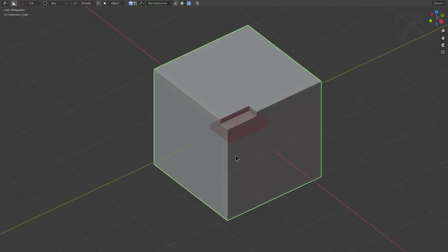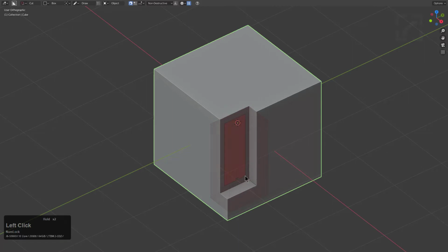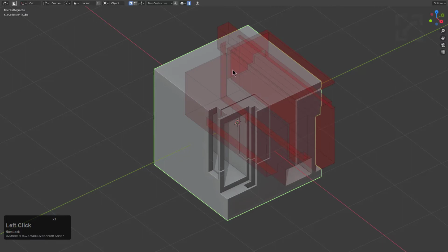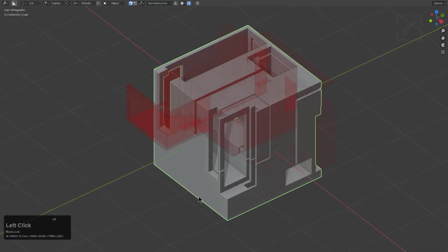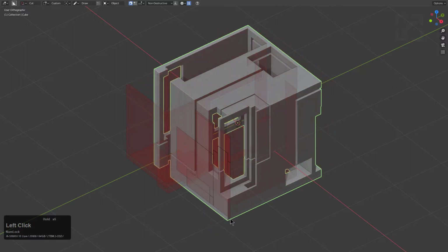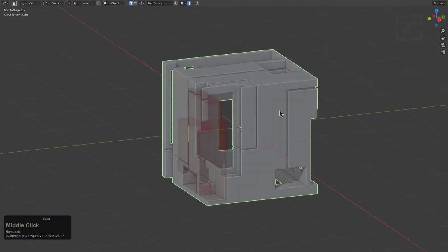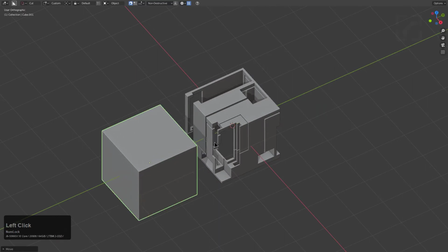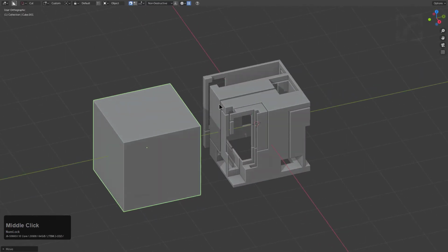So one way I like to work in Boxcutter is just drawing a shape, doing my usual box cuts, just working aside, just kind of being random, seeing what I get, and then of course drawing, pressing T to solidify, and then of course drawing a cut and extracting things out, and then repeating those extractions in other areas to kind of get something really random and see what kind of gifts you can get from the booleans that you've seeded it.